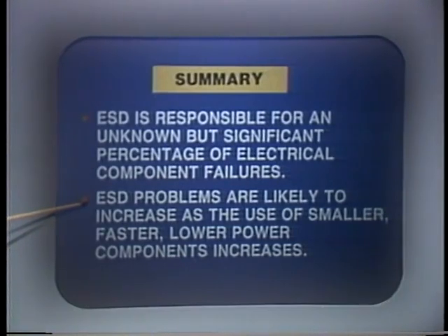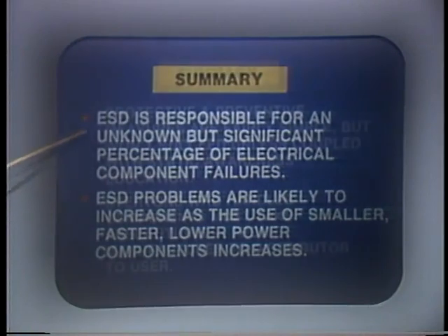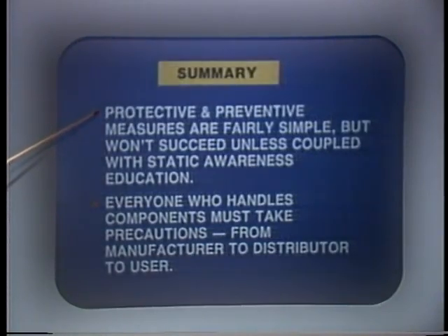Secondly, that ESD problems are likely to get worse as we use smaller, faster, lower power, state-of-the-art components. Third, that preventive measures are fairly simple, but they won't succeed unless everyone is static aware. And finally, that everyone who handles components and assemblies must take precautions all of the time.